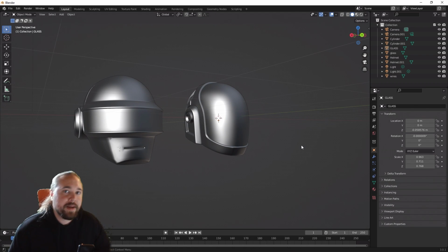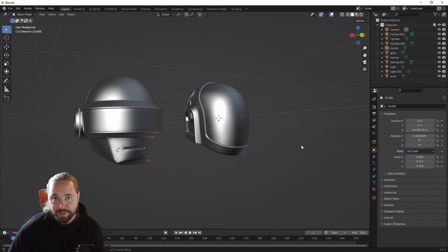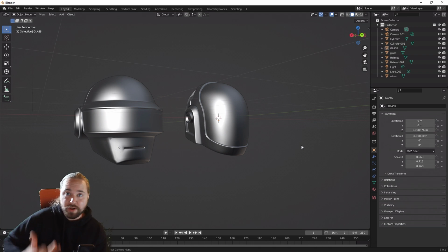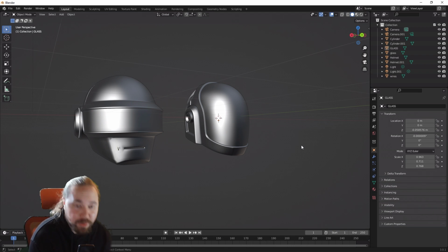If you bring in a model that is larger than 20,000 polygons, the assets that are provided by our 3D artists in the Enscape Asset Library are usually less than 20,000 polygons, so you can place them a lot of times and not worry about it. If you have a model that you want to bring into Enscape as a custom asset just once or twice or 5 times or whatever, you can go higher than 20,000 polygons. You can go with 100,000, 200, 800,000 polygons, and it will still work.